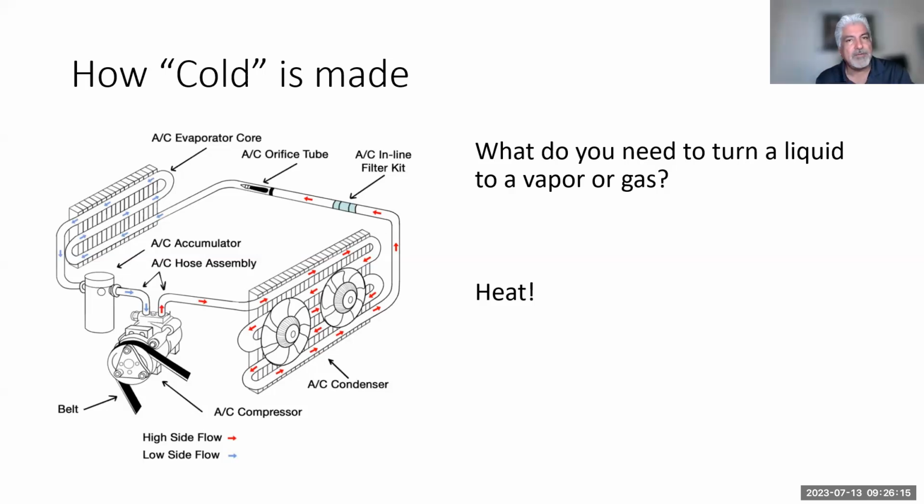So therefore you may want to take interest in installing one. If I do pull an orifice tube and that orifice tube is full of metal or full of whatever, I'm going to try to see what I can get out of it. But if not, then maybe it's time to put in an AC inline filter kit, because you're trying to protect the number one component there that has the moving parts, and that would be the compressor. So, Tony, definitely take interest in that.